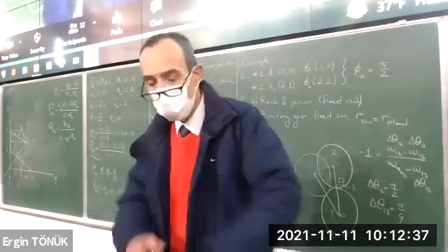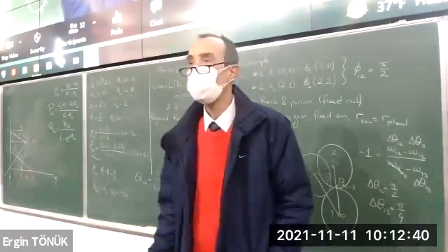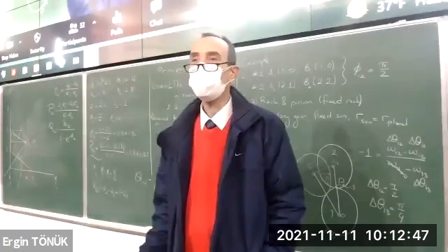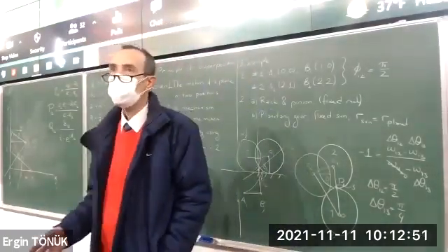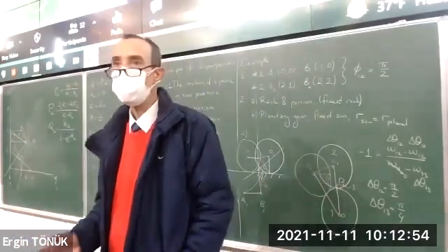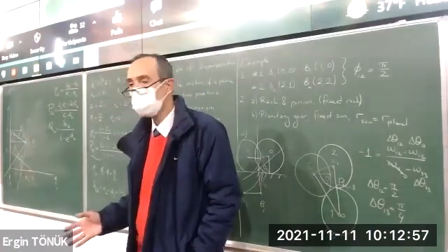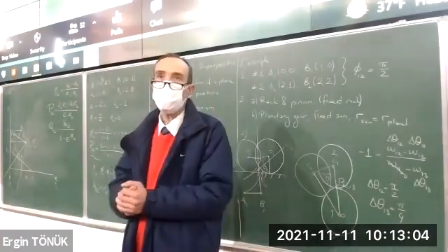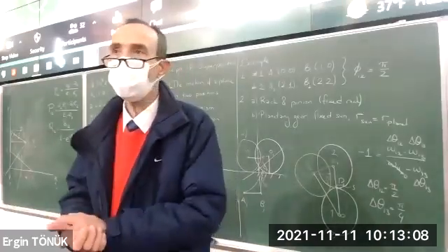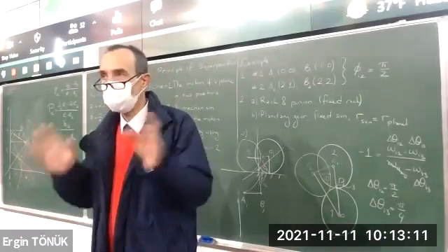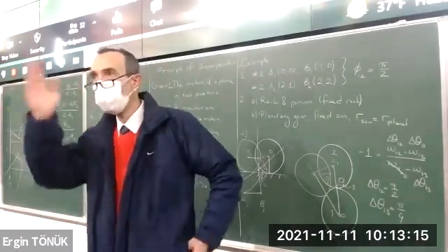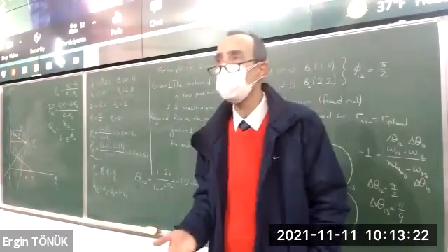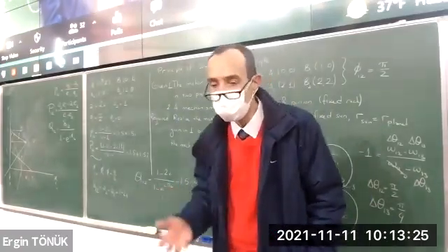Depending on how we select them, we find A0 and B0 on perpendicular bisectors. So we are more free to select A, B, but we have restrictions on A0, B0. The brute force method, if you would like to specify A0, B0, or if it's bound in a place, is maybe you can just change the position of A in 2 positions and move the perpendicular bisector and try to have it within desired area. But that's not something smart. We have a smarter way.